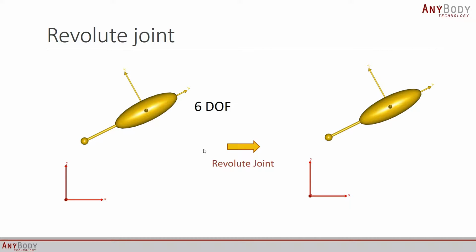Now, when we created the revolute joint, we supplied two reference frames to the AnyRevoluteJoint object, and these were the ground reference frame and a reference frame that was associated with this ground connection node on segment 1. And the purpose of creating the joint was firstly to make these 2 points coincident, which means that you wanted the vector r to be of 0 magnitude. So all three components of this vector had to be 0. So this would have arrested the three translational degrees of freedom.